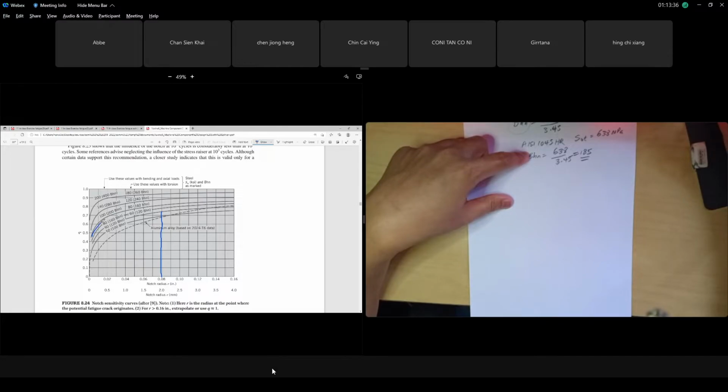Sketch with a pencil a line between the 160 BHN and 200 BHN lines, parallel and flowing the same way until it intersects. This is the line for 185 BHN. Bring it to the right and it becomes about 0.8.